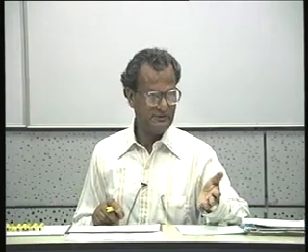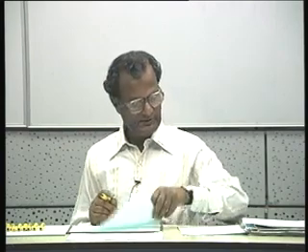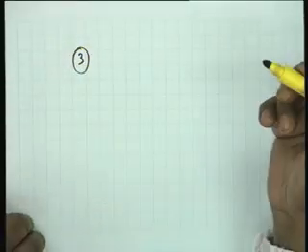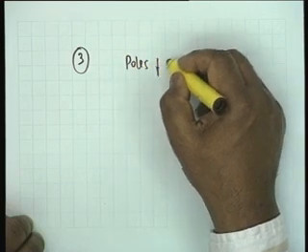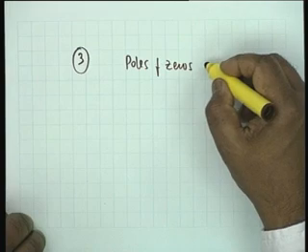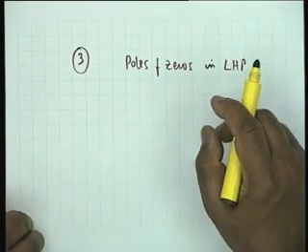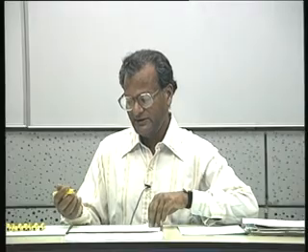But f1 plus f2 is definitely PR. In terms of a circuit, it means series combination or parallel combination of two elements or two positive real functions. The third property we stated is that poles and zeros of PR functions must be in the left half plane, because the right half plane will lead to instability and therefore a violation of the real part condition.